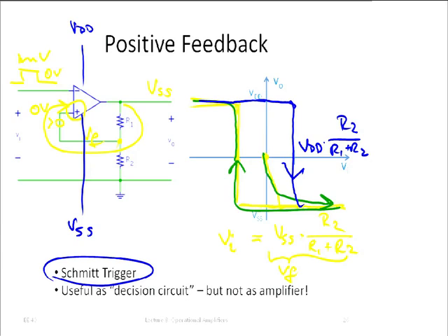So then we actually want a circuit like this. This characteristic here is called hysteresis. We turn it on, and then it stays on for a while until we really want to turn it off again. For example, with the thermostat, we may give it half a degree. The temperature has to not only drop back to 20 degrees, it has to drop down to 19.5 degrees. Only when it is 19.5 degrees do we turn the heater on again, and we turn it off only when the temperature is 20.5 degrees.